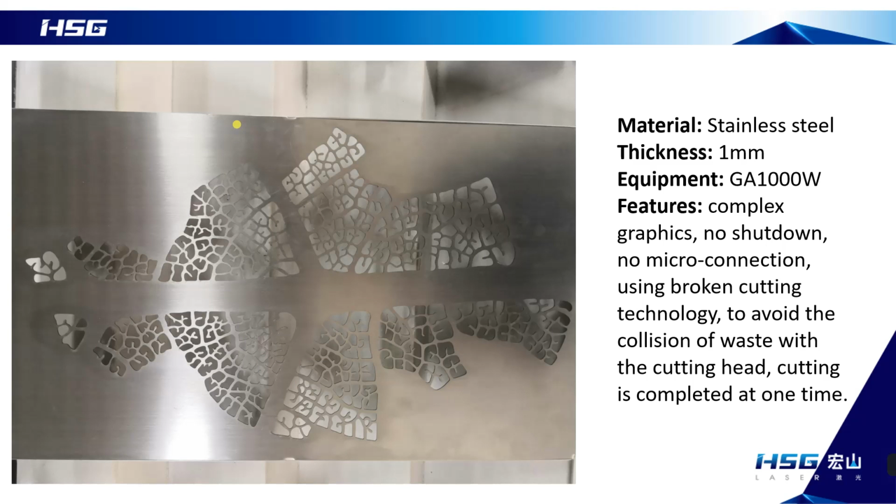In this case, we can also use the broken cutting process to cut all the lines on the inside and then cut the figure on the outside. After that, the whole little figure can fall off completely. Avoid laser head collision. One-time completion of cutting. Do not need to pick up materials manually.